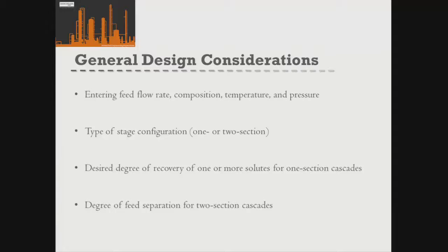Okay? But as I mentioned right at the start of this course, heating and cooling unnecessarily is expensive. Yep. So you would only want to think about that if you really had to, or you were very close to being able to get the composition you needed, and a little tweak in temperature would affect the tie lines to allow you to do that.